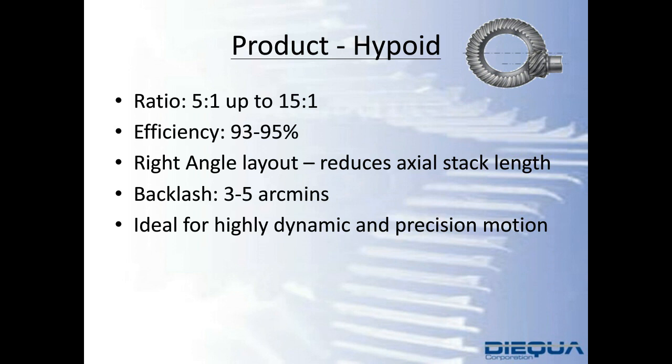Okay, the efficiency. The efficiency is 93 to 95%, right? You would ideally have a reduced stack as a right angle. Gives you freedom of compact design. It also allows for a hollow or a blind hole for mounting. It allows you to secure and pilot the pinion gear, for example, or the lever arm onto the unit. Let's see here.